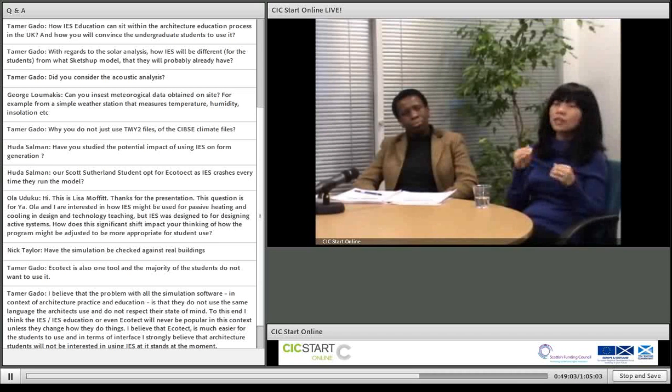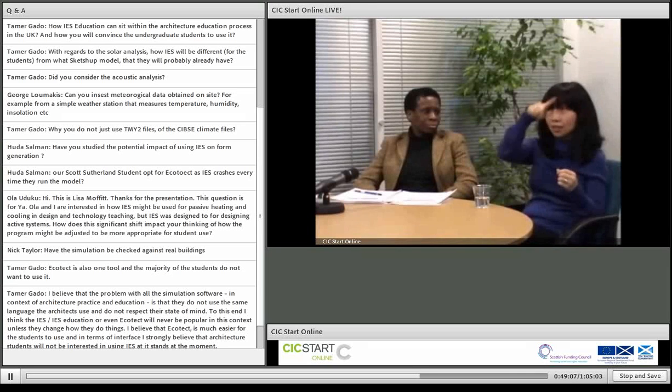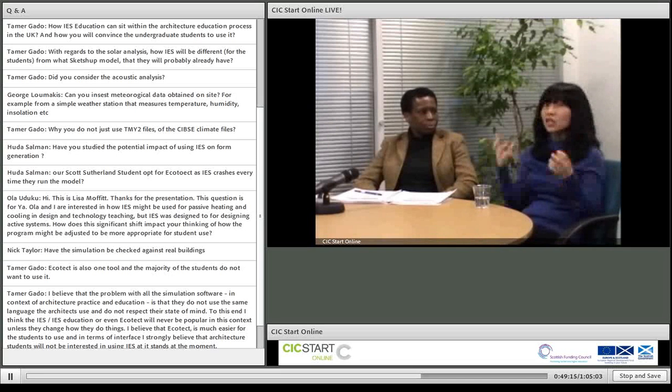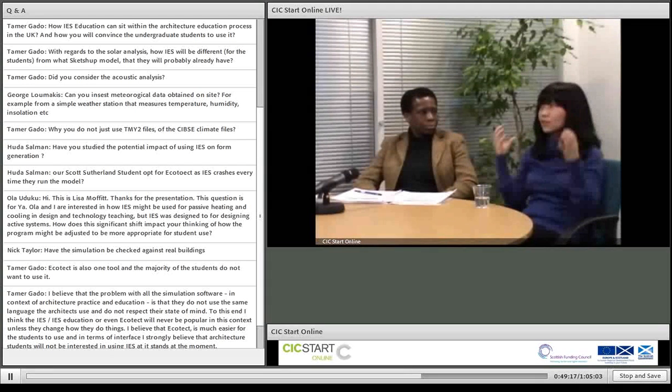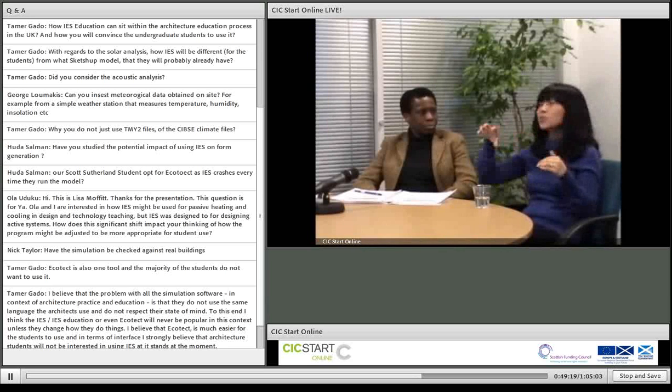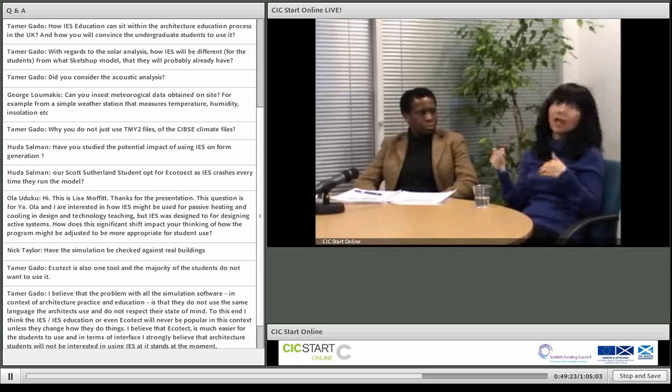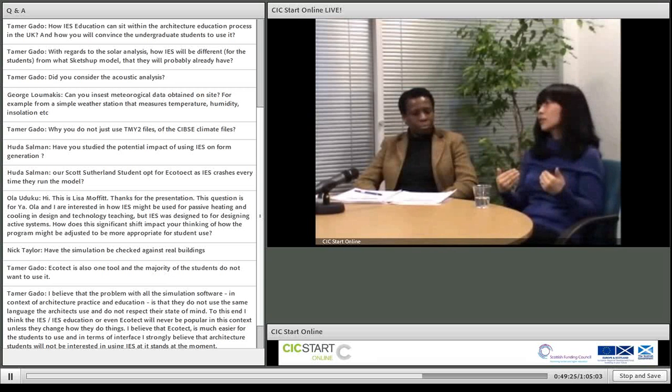In Vista, when you look at the results, you can see graphs of the predicted data, for example air temperature or energy consumption, and then the measured data from the BEM system. In just a few seconds, you can plot the predicted data and measured data so you can compare. That's actually a calibration. At the moment we can do small steps, we can do hourly calibration.